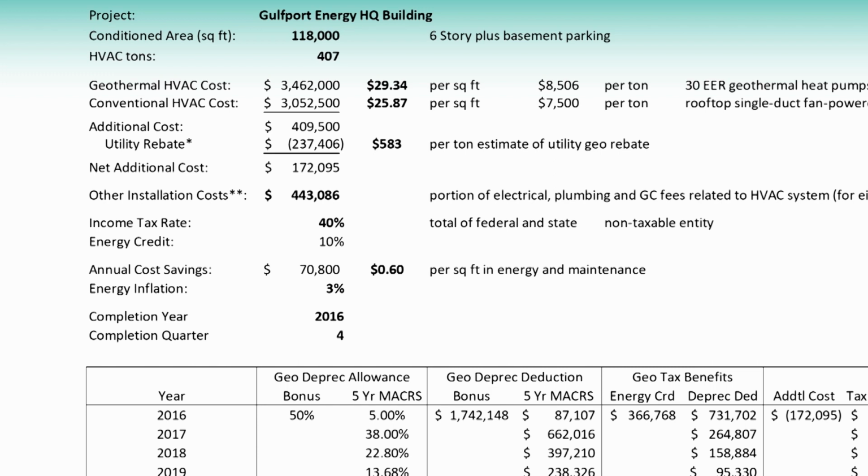They aren't that complicated. You don't need a bunch of modulating controls and all this stuff that forces you to full-on DDC. You turn heat pumps on and off, stage 1 to stage 2. You turn it to cooling mode or maybe extra dehumidification. That's all from a stat. We monitor the system pumps. We schedule on fresh air units. All these things can be done with these web-based tools. So that's in the number.